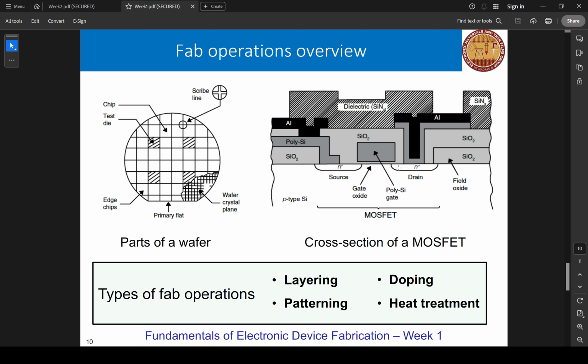In a 2D material, here this whole thing is silicon. A 2D material is a very thin semiconductor, one or two layers, where the thickness would be 1 nanometer or even less. That itself replaces your whole wafer. The conduction, the on state, off state, everything is through that material.